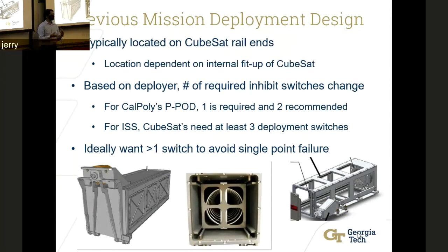As I mentioned, these CubeSats are put into pods. The pod that we're using for this mission is the JSSOD, supplied by JAXA. It's an orbital deployer for small satellites. The picture to the far right, I guess far left, over here, this one right here is the JSSOD that we're going to be utilizing. As you can see, there's space to fit multiple CubeSats in there. There's a total of 3 1U CubeSats that we can properly fit in.